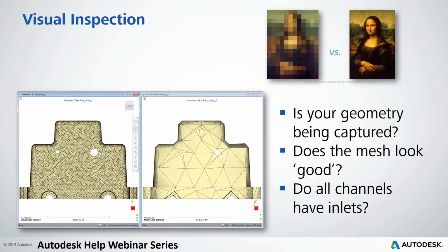Now, I did mention that we recommend a visual inspection whenever you first import the part and mesh it. It's kind of like a pixelated version. Up on top, you can see the image in the pixelated version, but you really see it when it's more defined. It's the same thing when it carries over to the mesh that Moldflow applies, and the same with Advisor as well. If you're seeing square, boxy features instead of rounded features, that's typically a telltale sign that you should try increasing the mesh resolution to capture that geometry.